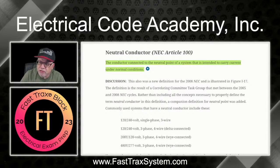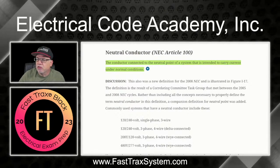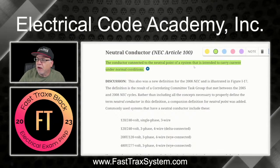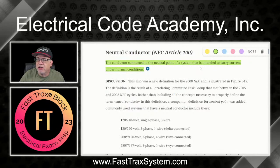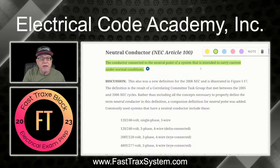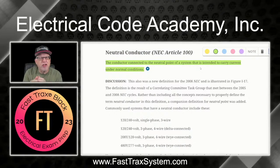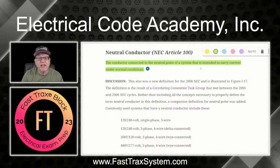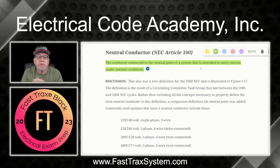All right, so let's look here. Neutral conductor. What's a neutral conductor? It's the conductor connected to the neutral point of a system that is intended to carry current under normal conditions. So if you think about that, it's that white conductor or that gray conductor or that conductor with three white or gray stripes other than green. That conductor is carrying current, and it's expected to carry current.